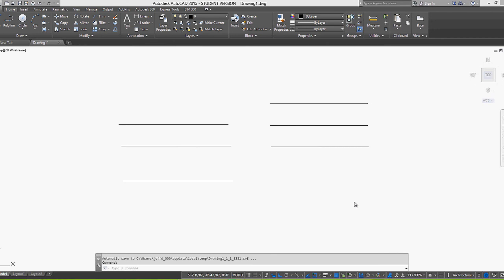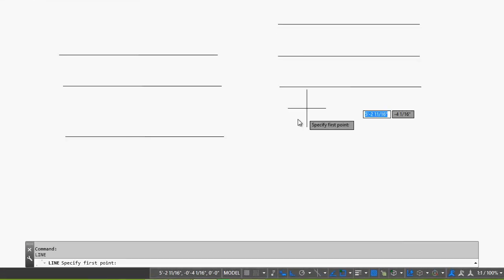That dash and those inch marks are optional. Okay, so if I do, let's say 1/2, okay, again, that means 1/2 of an inch. Automatically AutoCAD is going to associate no ticks with inches. Okay, so that's going to be 1/2 of an inch.